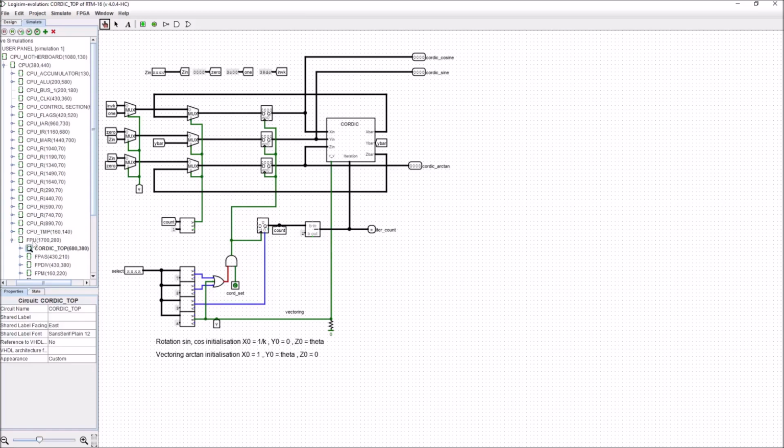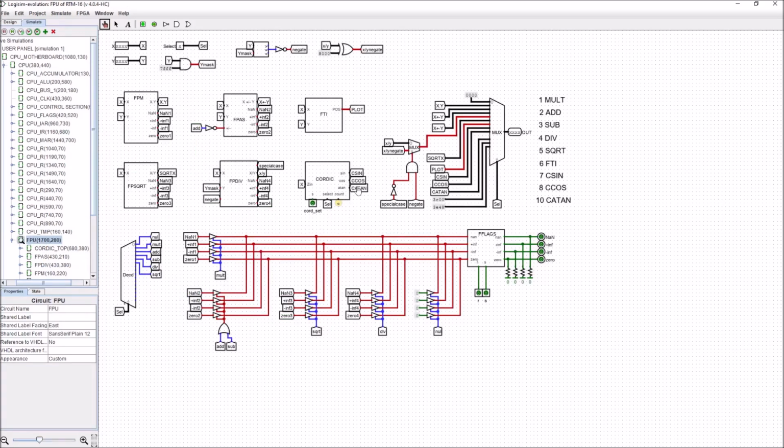The only reason we really need to put in the value for our A is whenever we have the very final value come out. And when that final value comes out, we're going to have to ensure that we pick off the cosine function to pass to the output. So we have to make sure that in the final iteration for the CORDIC that we choose this cos instead of the sine, and the cosine will get fed through here. So this select button will be at a value of 8, and the CORDIC cosine will get passed through instead of the CORDIC sine.